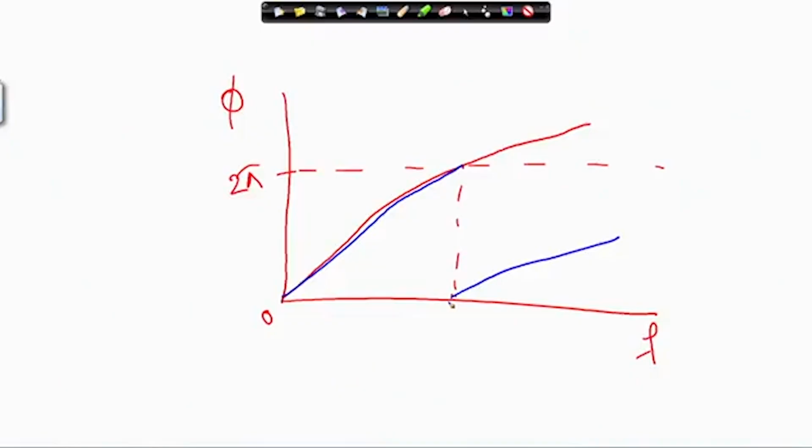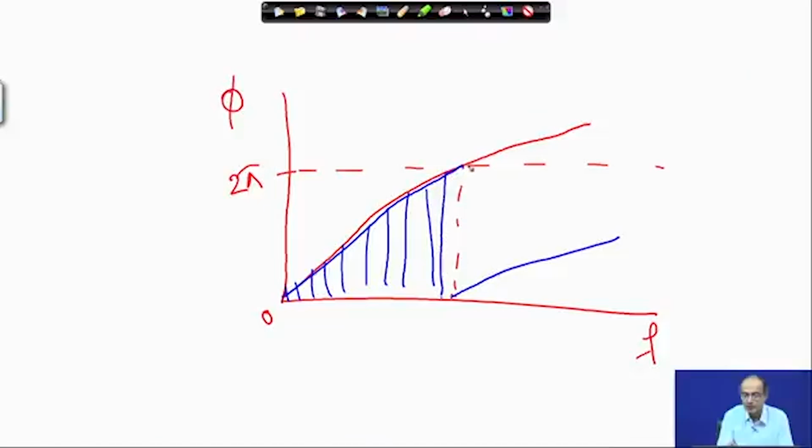The simple way this can be done is to follow, for each frequency, how much the change in the phase is. When, due to this complex transform, a jump occurs in the phase, the value of the jump is about 2 pi. So we know it is a huge jump. When such a big jump occurs, we simply add 2 pi and put it back in the real place.